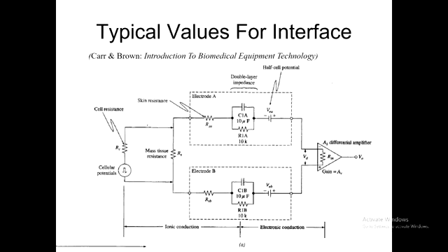In other words, from day one this year, we were looking at what resistance does this capacitor experience? What shunt resistance? It's not just R1A here, it's R1A in parallel with RS here, RSA, RT, RSB. Oh, hang on, that's in parallel with the other capacitor, right? So we've effectively got two capacitors separated by a couple of resistances.